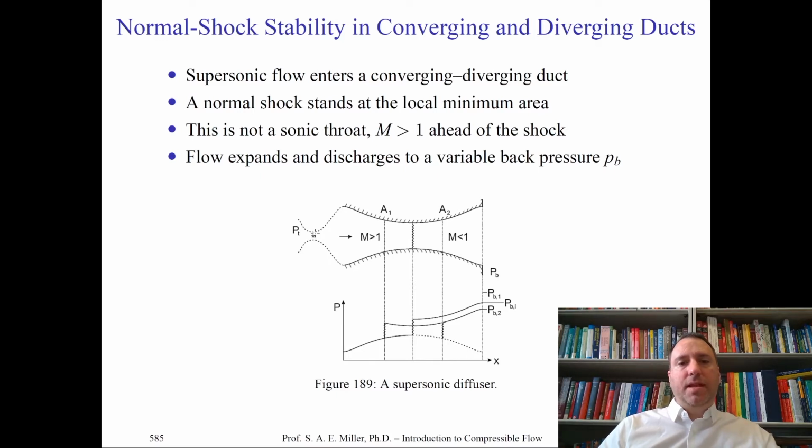Of course, then we need to raise the nozzle pressure ratio, and then the flow will be supersonic in here. But since we have a converging part of the nozzle, the flow will slow down. And then it will discharge through a back pressure. And so there's a number of solutions where, as we lower the cross-sectional area of the second part of the stream tube, then we have normal shocks forming. And that's what we put through the so-called supersonic diffuser.